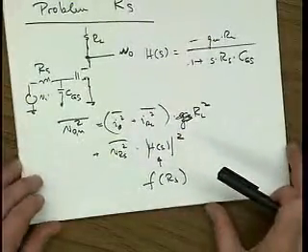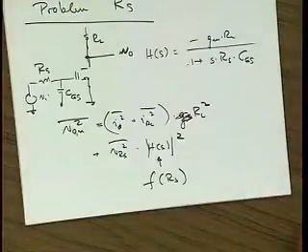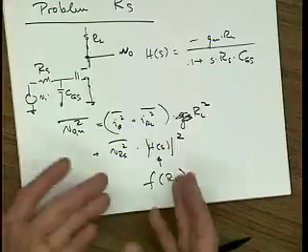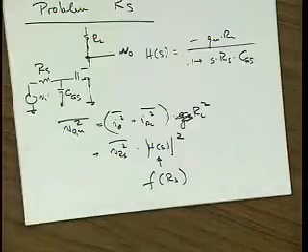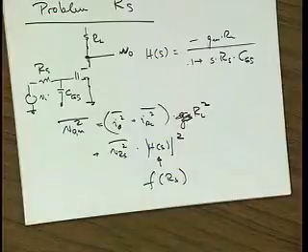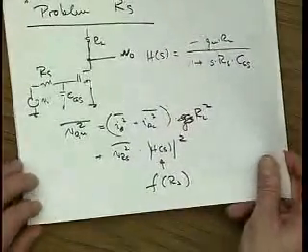And that's a problem, for example, with general purpose operational amplifiers. If you make an op-amp, you want to sell it, you have to specify how much noise it has, right? But you don't know what RS is. Whoever uses it will put whatever his situation demands, and so you would have to make an entire catalog of specifications for every possible RS, and obviously that wouldn't be very attractive.